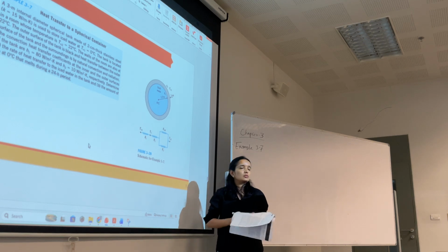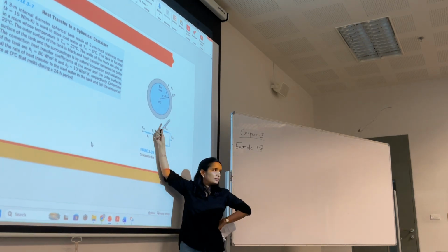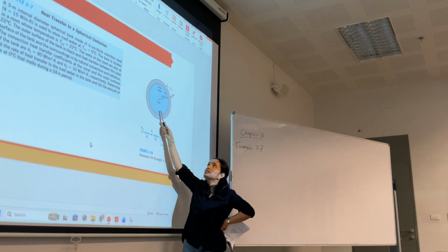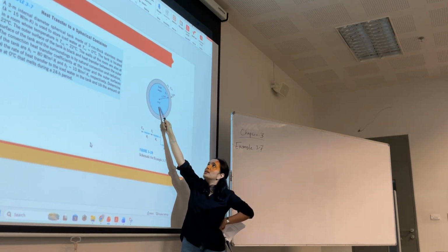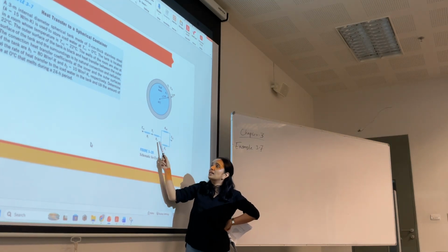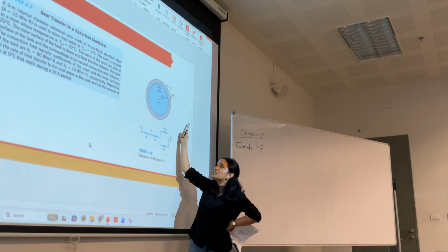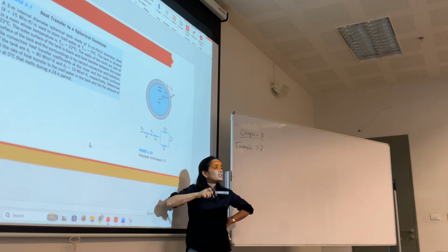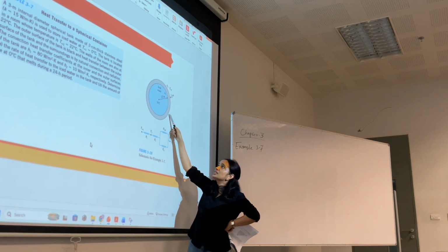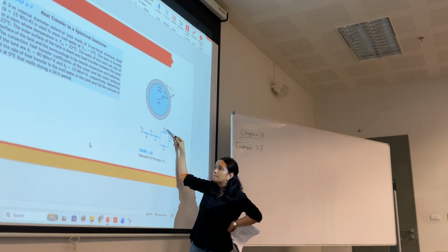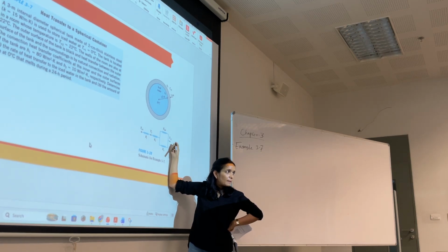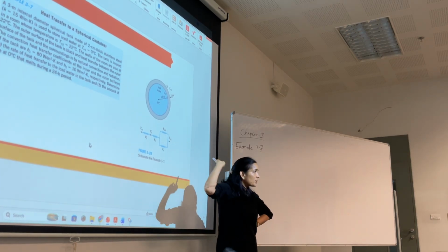Okay, so this is a tank. It is filled with ice. There is some ice, some water. So the heat transfer from here to here is convection. From here to here, conduction. And then outside we have convection as well as radiation. Radiation is mentioned in the numerical. So the heat transfer outside is parallel convection plus radiation. So this is why this circle.